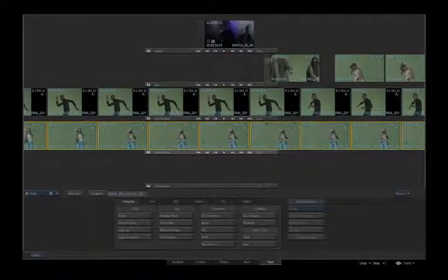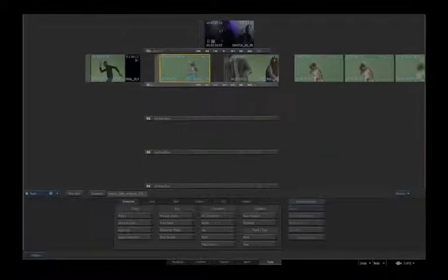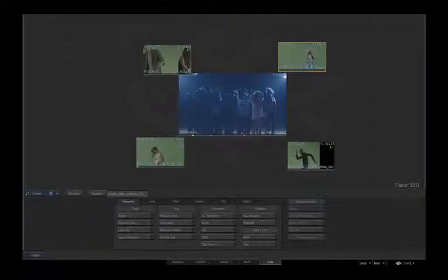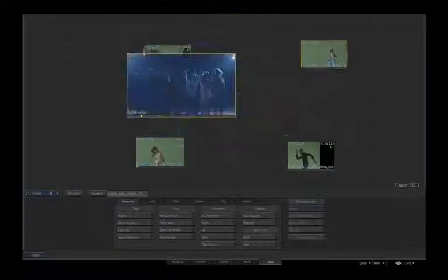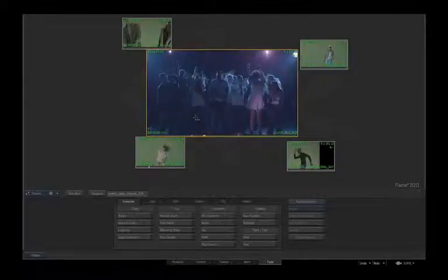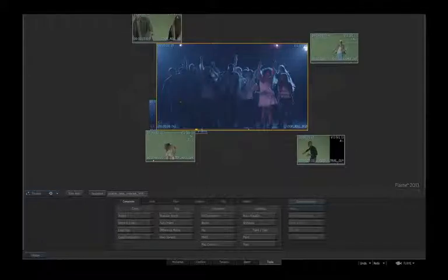But you also have some other tools, like if you want to, you could just put your clips here together on a reel and view them as essentially a source area or a set of thumbnails. This is a great way to just arrange things and scratch pad design things. You can also gang those clips if you want to be able to view them all together. So that's kind of neat. You could also subclip a section based on a mark in and out here if you wanted. That works well too. So back to the reels.